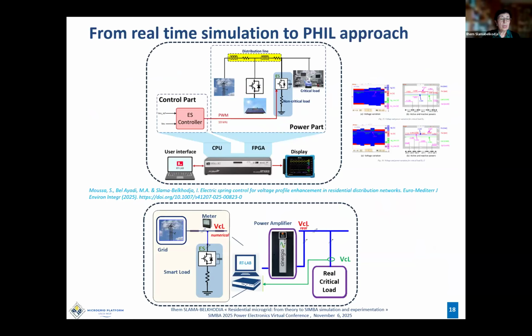Regarding smart load and its integration into the actual platform, we first moved on to the real-time simulation with programmed control on the CPU part of our simulator and the rest at the FPGA level. The results were published in the paper cited on this slide. We are currently testing the PHIL approach in which smart load is in the simulator and the voltage at its terminals is amplified to be connected to a real critical load.